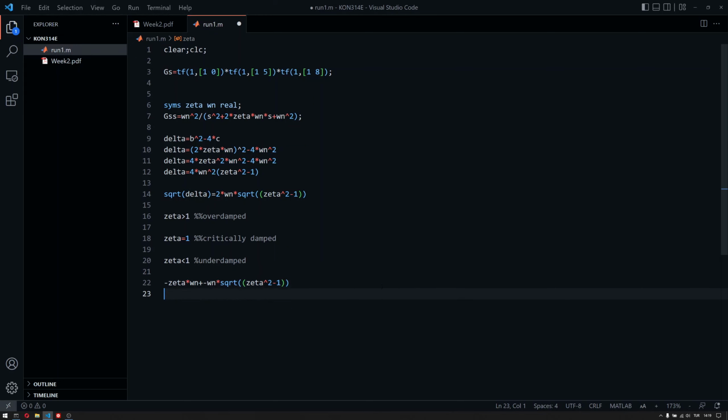Now, we also have this omega n squared in order to have a gain of 1 if you use the final value theorem on this transfer function. Applying a step input, you'll see that plugging in s equals 0, or s tending to 0, will give you omega n squared divided by omega n squared, which is equal to 1. So this is an ideal transfer function that we think about if we are talking about second order transfer functions.